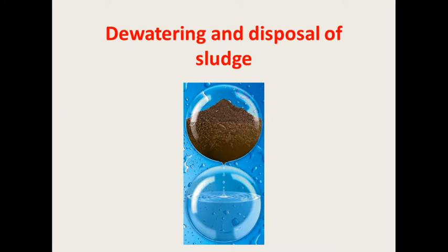What happens at the end of this process? In anaerobic sludge digestion, the organic matter or sludge is converted into CO2 carbon dioxide, then CH4 methane plus new cells plus energy for cells, then other products like hydrogen sulfide, H2 and N2. This is the overall final reaction of anaerobic sludge digestion, and the various processes which occur are hydrolysis, then acidogenesis, then acetogenesis, and methanogenesis. We already discussed all this in the previous topic, anaerobic sludge digestion.